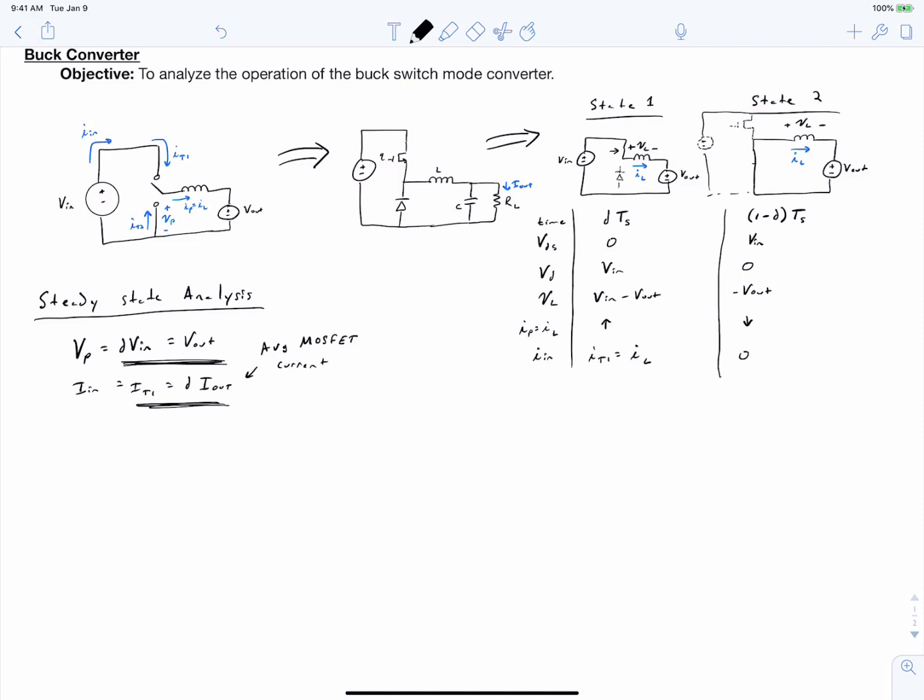So next we can do Kirchhoff's current law around our throw 2 current, our average throw 2 current, and we can establish this as a supernode equation where clearly the sum of our throw 1 current plus our throw 2 current must be equal to the average of our pole current, or our output current.